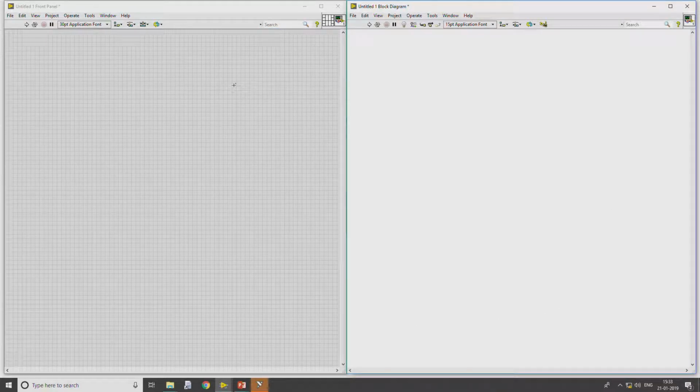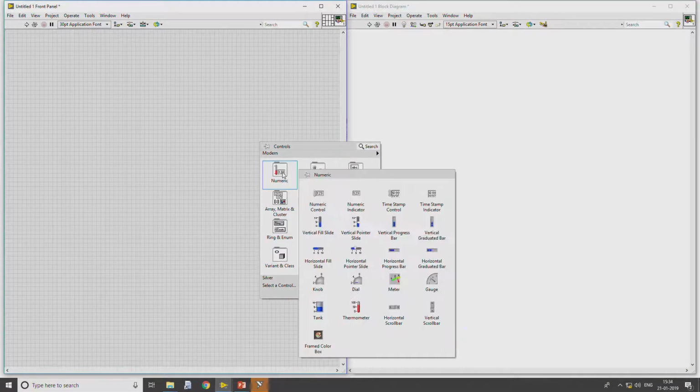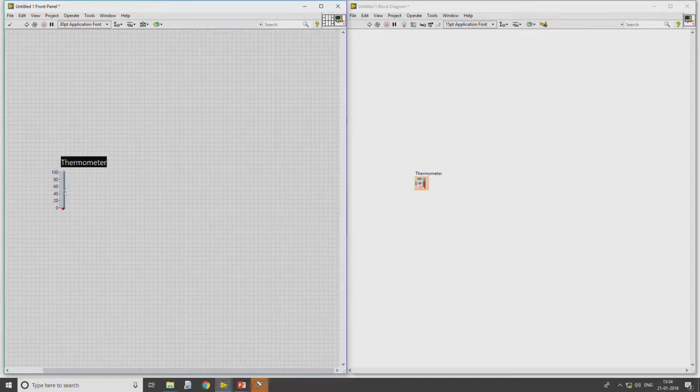Now, what we require is to connect our controller unit, one being the error detector and the other the controller, in the LabVIEW environment, and then interface it to the real world. As our application is similar to a temperature monitoring application, I will take one input, the set point. I will rename it as set point.